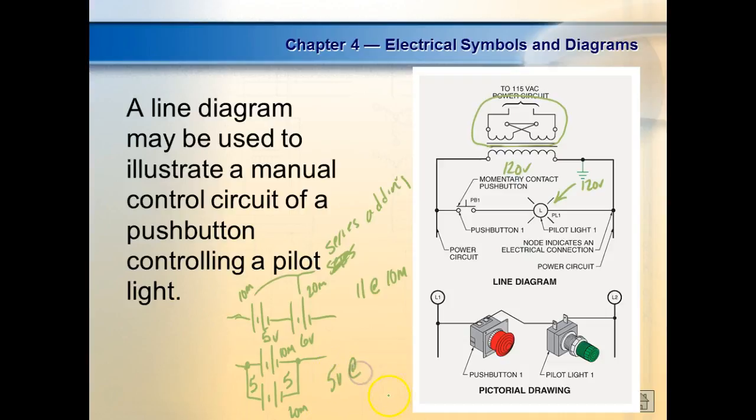And what would our current be? It's going to be 30 milliamps. So in parallel, the current adds. If I hook batteries or cells in parallel, we increase the current carrying capabilities of the batteries, but we don't increase the voltage. If we hook them in series, we do what? We increase the voltage, but do what?